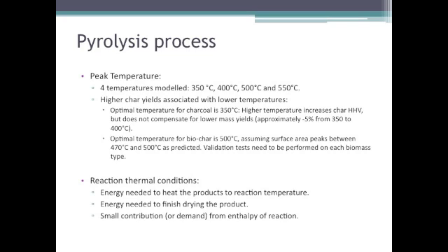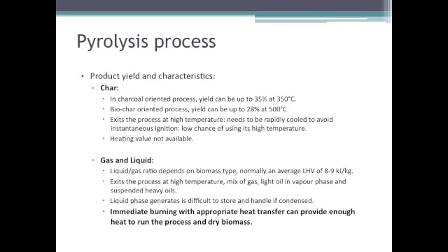Yeah, the thing is that it's because of the thermal behavior of surface area, because the other parameters are important as well. But what I saw was that the other parameters had a softer behavior with temperature. They change more softly. But in terms of surface area, it was really low until 400 and some degrees Celsius, and then it peaked really fast at a certain temperature. That's why it's not the most important parameter for biochar probably, but it's the one that changes the most with temperature, making it the bottleneck for choosing biochar temperature.